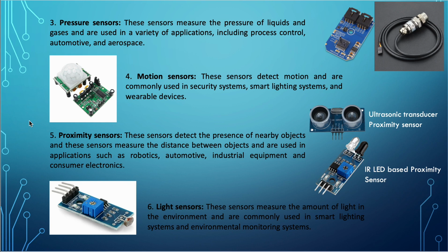So then you will see the requirements. For example, the main entrance, I need to cover a 6 meter area. For the main entrance, the door is big, there are a couple of doors to enter that building, so that needs to be covered. The other areas, I only need to cover 2 or 3 meters in front of the door, right? So you look at the requirements, and if you Google motion sensors that are available in the market, you will be presented with a set of products.